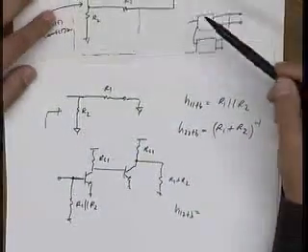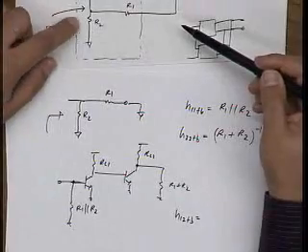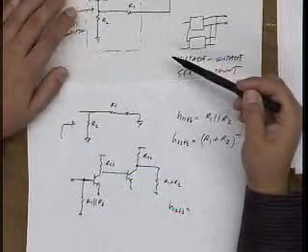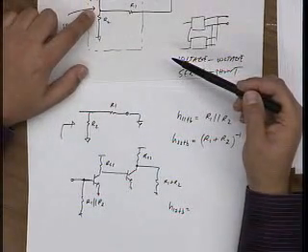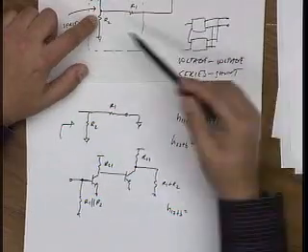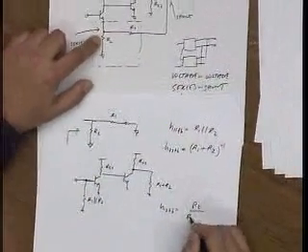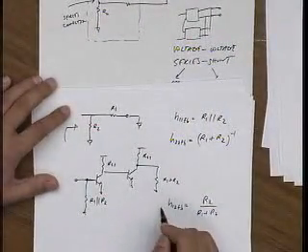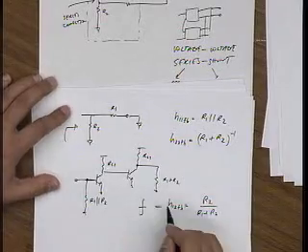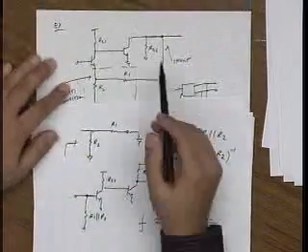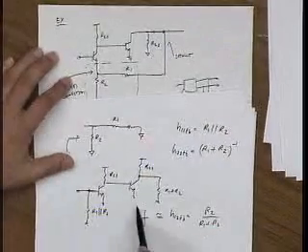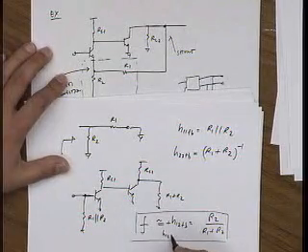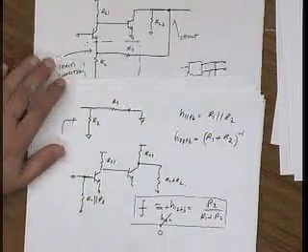And then what's the feedback factor of the feedback network? Well, I drive the output with a voltage. I leave the input open and just look at the voltage that appears at the input. Well, that's just a simple voltage divider. It's R2 over R1 plus R2. Okay. And because we assume that the reverse feedback of the amplifier is almost 0, then the overall F is just determined by the feedback network, right? I should add H12 amp, but this is mostly 0.